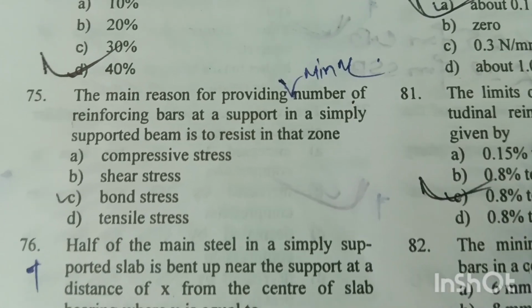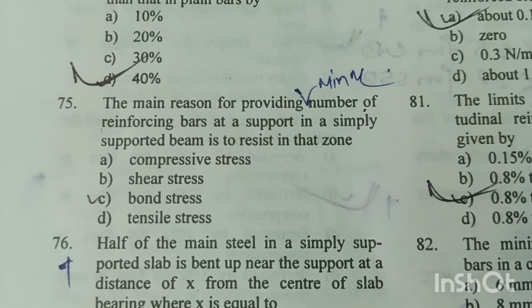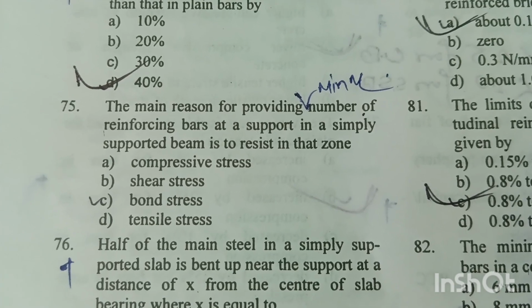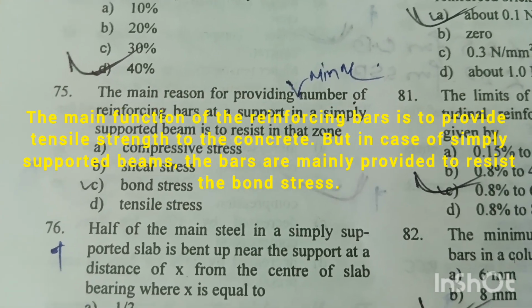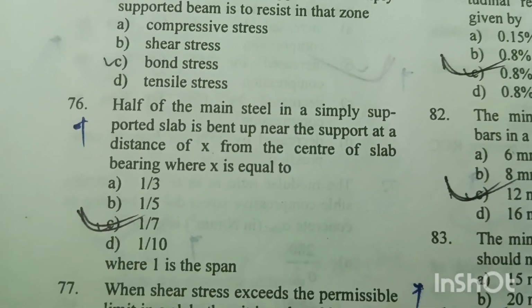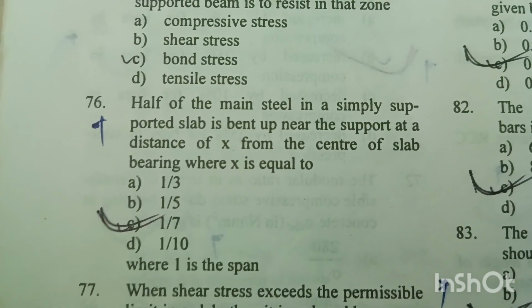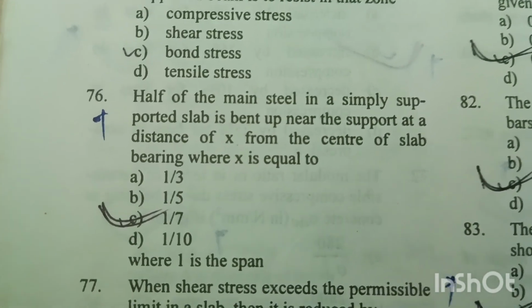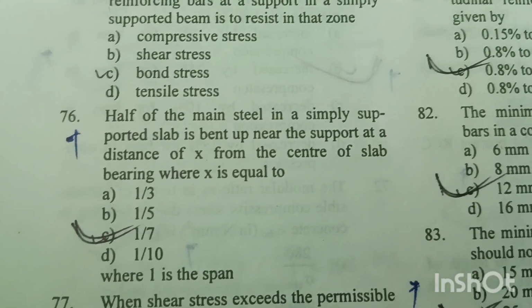Question number 75. The main reason for providing minimum number of reinforcing bars at a support in a simply supported beam is to resist bond stress in that zone. Option C is right answer. Question number 76. Half of the main steel in a simply supported slab is bent up near the support at a distance of x from the center of the slab bearing, where x is equal to L by 7. Option C is right answer, where L is the span.